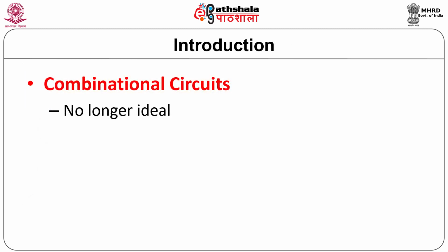In combinational circuits, the output of the circuit is dependent on the present input combinations. This statement is true with the assumption that the circuit is built using ideal logic components. Ideal behavior assumes that there are no propagation delays in the logic gates and other building blocks.